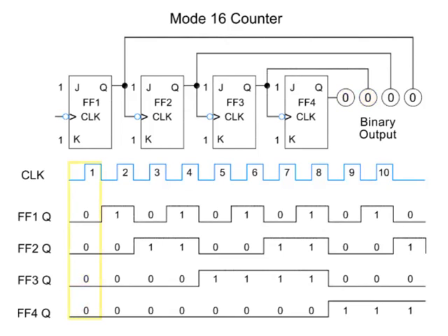As pulse 1 arrives at the clock input at flip-flop 1, it toggles on the negative edge. The output at Q1 will go from low to high, or 1. Thus, the counter will be at 0, 0, 0, 1. When clock pulse 2 arrives at flip-flop 1, it returns output Q1 back to 0, which causes flip-flop 2 to toggle to 1. The output at Q2 is 1, and the count on the display now reads 0010.